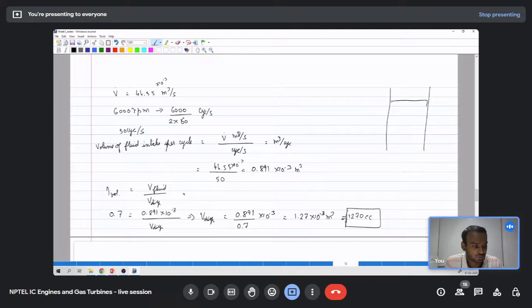Okay. So the piston will be something like this. There could be like 3 piston rings. Ideally we need to seal the gas completely, and we should also keep the piston moving. If the piston is the exact diameter of the cylinder or the liner, it will be very tight to move.